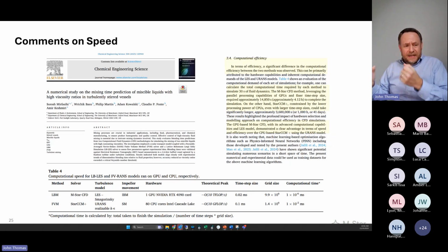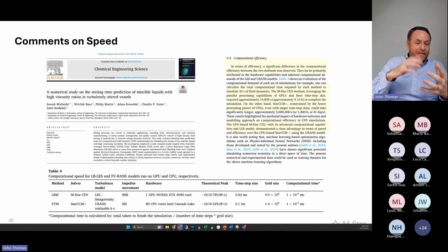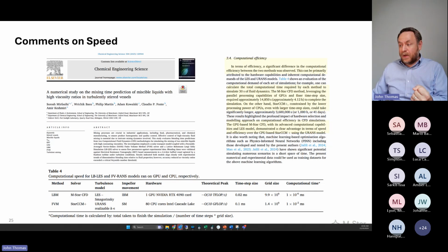What's really bringing this some punch is the fact that when you put it on these GPU architectures, you get better physics. You're getting 10 times the resolution at a fraction of the time step, which is important for reaction, suspension, kLa, mass transfer. This isn't a moral victory. There is utility, especially in a multi-physics system, in being able to use a smaller time step.